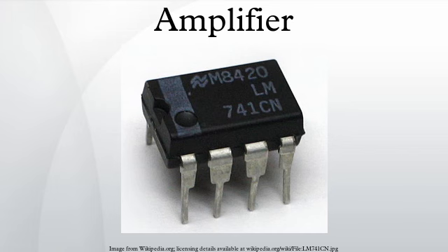Direct-coupled amplifier, using no impedance and bias matching components. This class of amplifier was very uncommon in the vacuum tube days, when the anode voltage was at greater than several hundred volts and the grid voltage at a few volts minus. So they were only used if the gain was specified down to DC. In the context of modern electronics, developers are encouraged to use directly coupled amplifiers whenever possible.